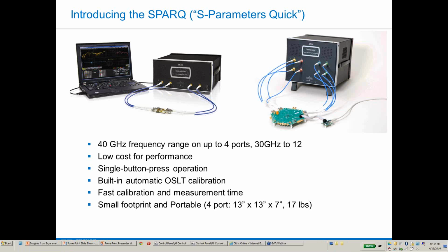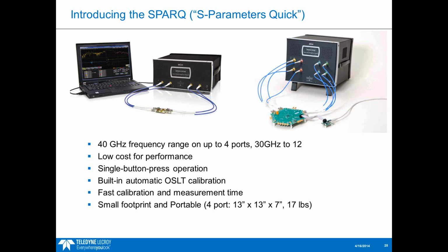Greg asked, I think while you were back on slide 7, what is the relationship between Nyquist frequency and data rate? So if you have some non-return-to-zero signal, which has some bit rate, that's the standard communication used today for things like USB, PCI Express, Ethernet. The bit rate is going to be double the Nyquist frequency, so the underlying clock rate is going to be half of the bit rate.